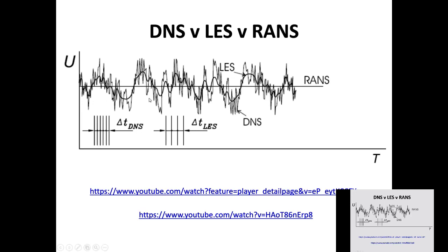That's more or less your actual velocity field, the actual velocity U. In large eddy simulation, you even it out a little bit. You get the shape of that curve at a macro level. I would say this is a micro level analysis, and this is a macro level analysis. But at the end, you fluctuate about this average line. So Reynolds average Navier-Stokes says, okay, that's my U.